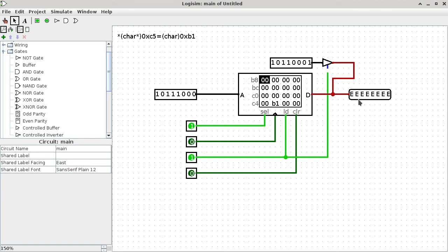So what we need to do here is to introduce an inverter, just a regular NOT gate. Okay, so just a regular NOT gate. We'll put it here. So this way, when we specify that we are reading, then we are also at the same time telling the control buffer, okay, just ignore, just let it be.